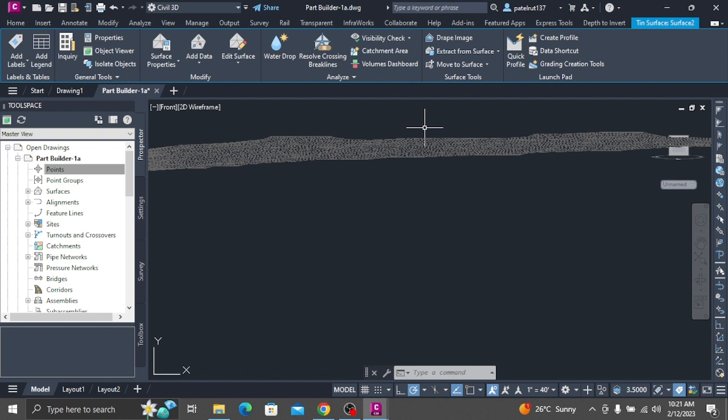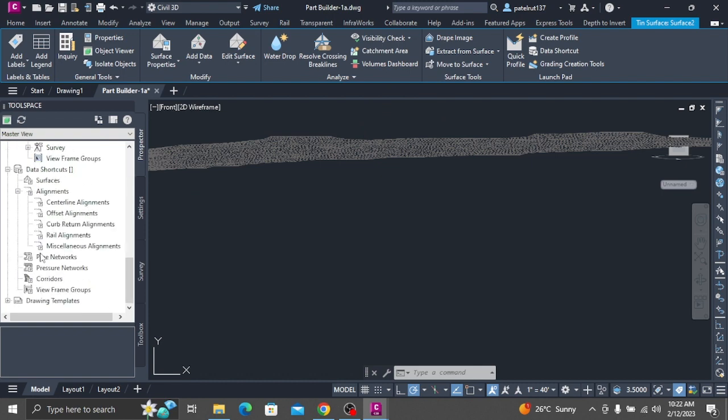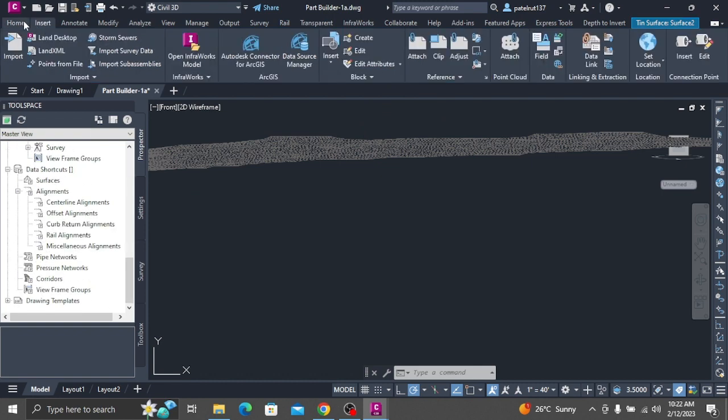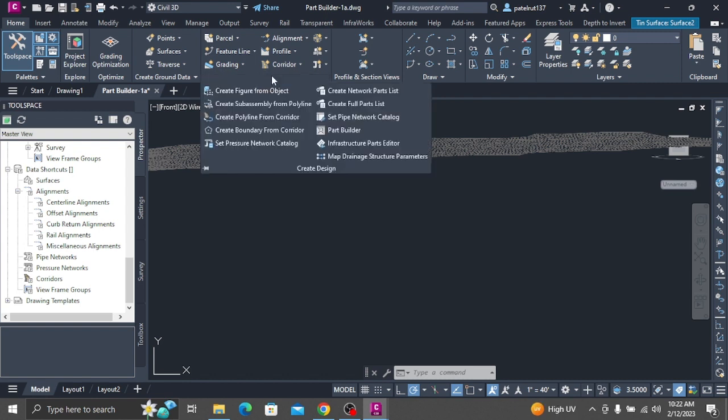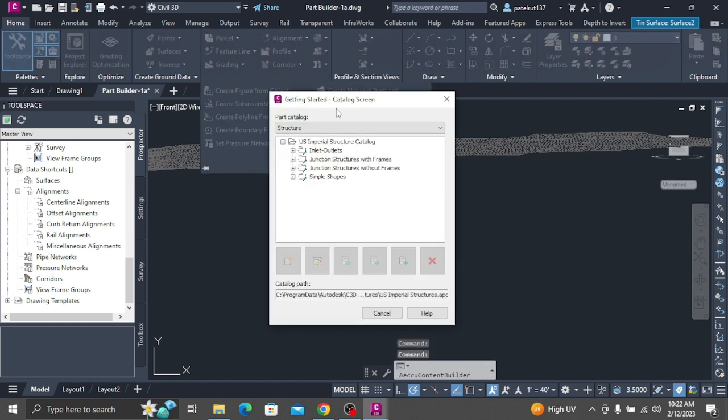Repeat these steps to create an extrusion modifier for the inner rectangle using a distance of 9. An extrusion modifier is created for the inner rectangle. Right-click Model Dimensions Add Distance. Click one of the vertical edges of the outer box extrusion. Click a point to set the location of the dimension. Len B1 is created for the height of the frame section. Repeat this step for the inner box extrusion. Len B2 is created for the height of the opening extrusion.